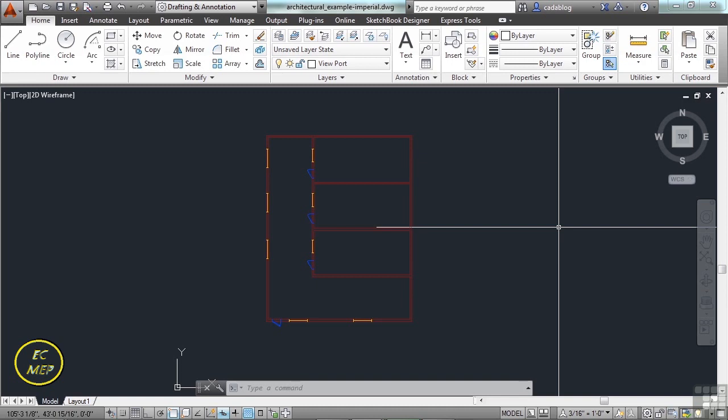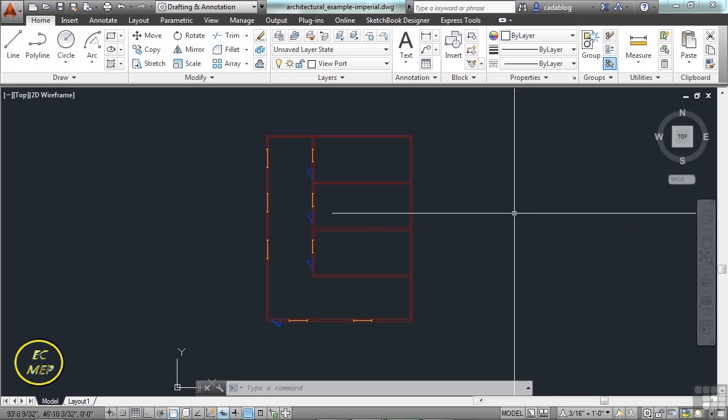Well, if you do that, then an object that's turned off or that's on a turned off layer is invisible, but it will still hide objects when you use the hide option. When you turn layers on and off, the drawing is not regenerated. Now, freezing and thawing something, that's a little bit different. Objects on frozen layers are still invisible, just like when they're off, but they do not hide other objects.